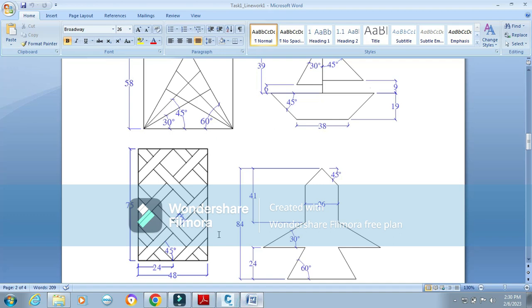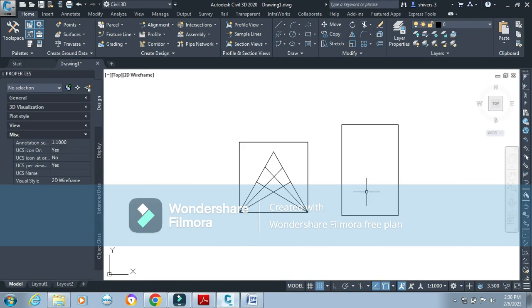If you look at it, it's like a plot, a structure where one goes under, one goes over. The first one starts at 24 and all of them are 6 wide. So you go line, press F8 to get straight, 24, enter, take off your F8, you know it goes at a 45 degree angle, so say 45, tab 135.